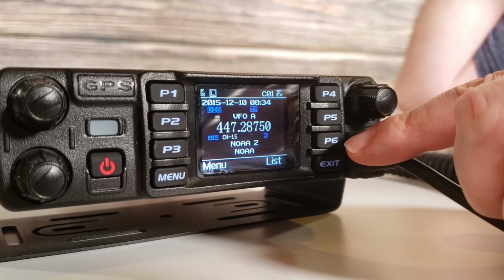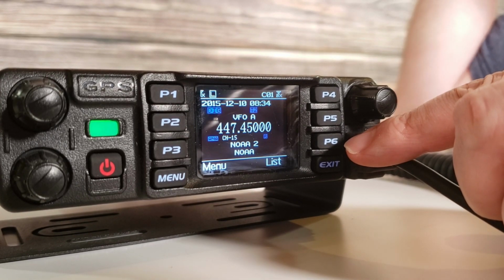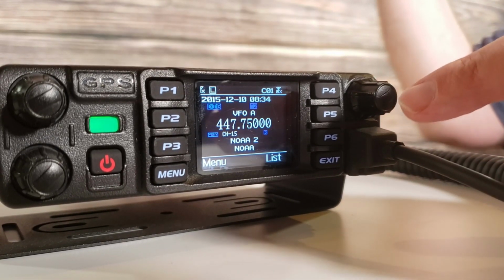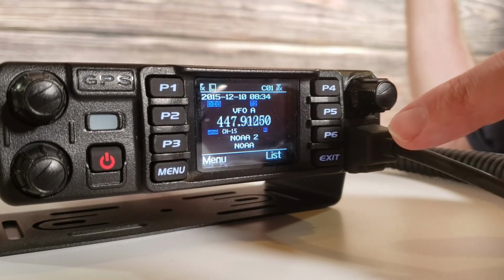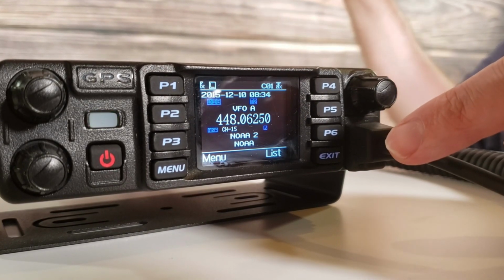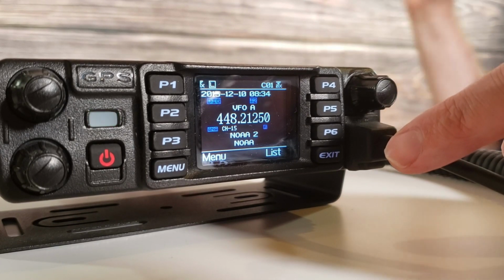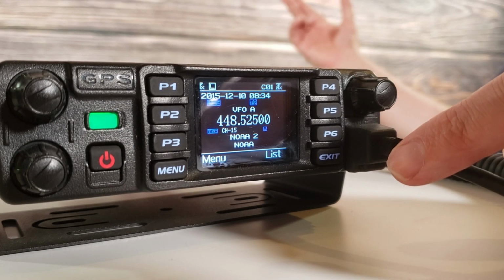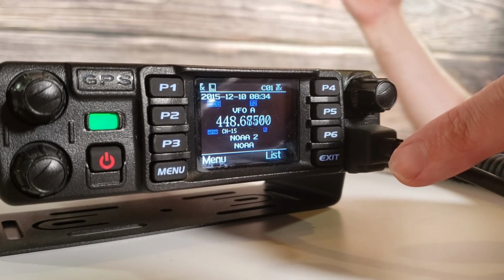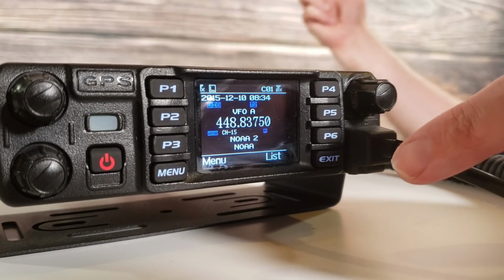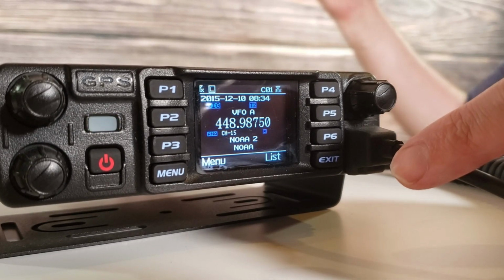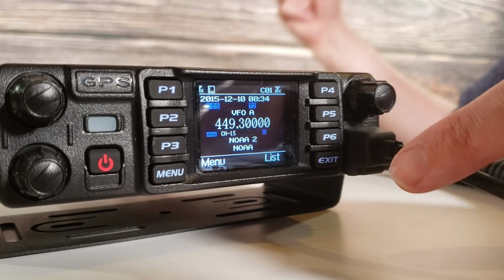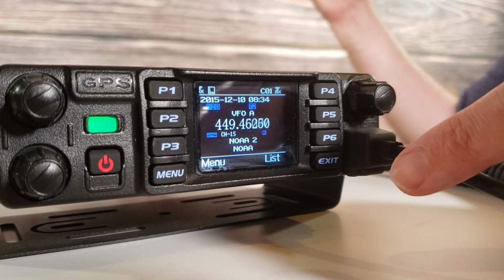What you may want to do is subdivide your channels out into zones. Namely, a channel that you create in CPS can only be assigned to one scan list. So in other words, you're going to have to duplicate that channel entry somewhere in the scan list and somewhere in another zone if you want to use that same frequency in a separate scan list. So mind the zone that you're in when you go to push the scan button, and mind the frequency you're on, because whatever that particular VFO channel is set for, the scan list that it's set for, you're going to get that scan list when you push the scan button for that frequency. And that's how it's subdivided.